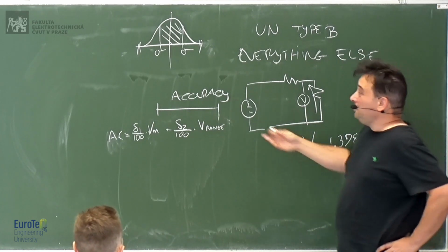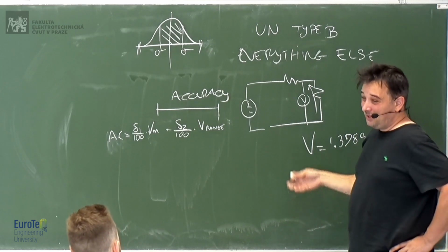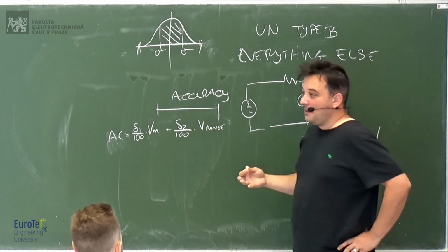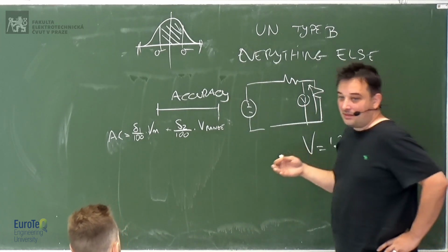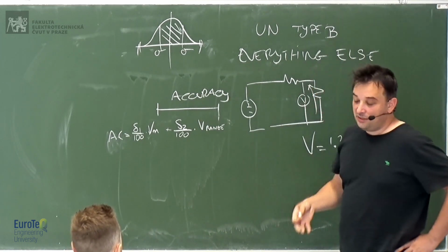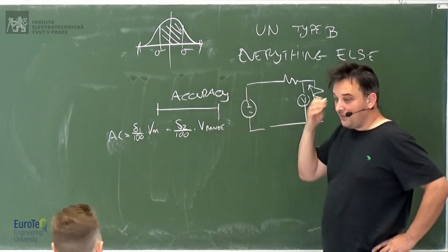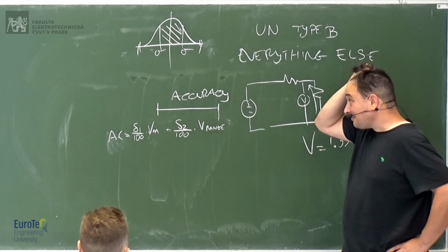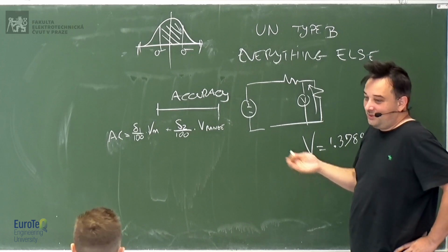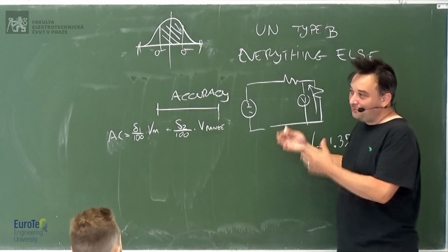The problem is that typically we don't know the actual distribution, and manufacturers don't really disclose anything like that. Either you make a calibration, so you take a precise source of voltage, change it, and see how the readings distribute. But that would be insane. In typical everyday life, you don't do it. Otherwise you would be a metrological institute and not somebody who uses a voltmeter.